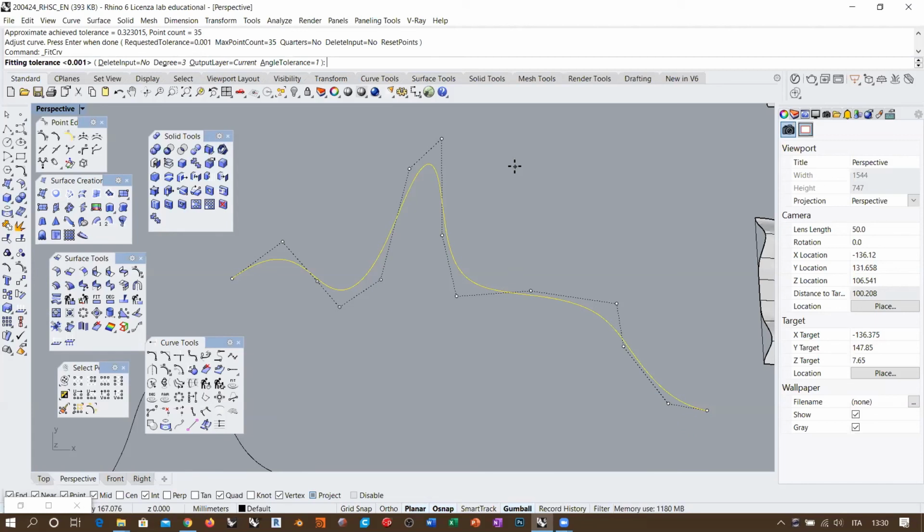If you don't control it, the risk is that you get a different set of spans between two curves. And if you want to work with a sweep two rails, you should have an equivalent topology for the two rails in order to avoid twisting of the surface and different speed along the rails.